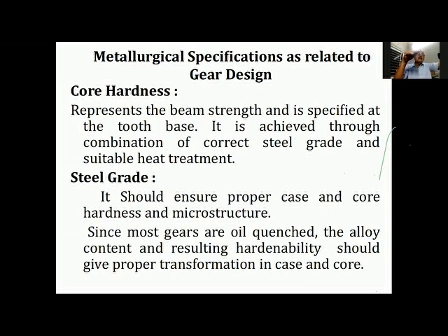So today, people who earlier specified as wide a band as 27 to 41 HRC or 30 to 43 HRC have mostly started specifying either 34 to 42 or 35 to 43 HRC, because it covers both these peaks of best fatigue performance.